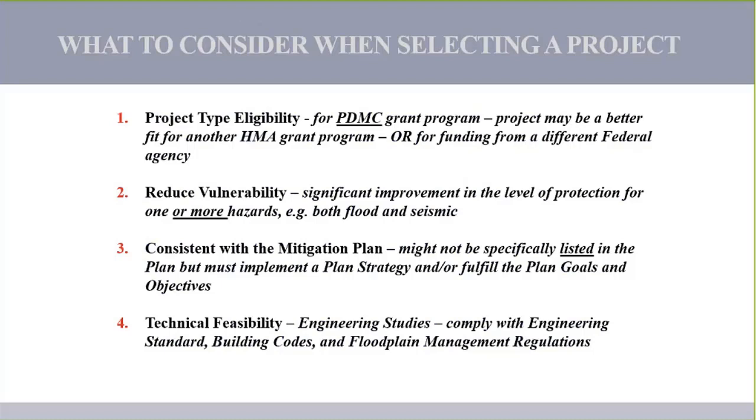Reduce vulnerability would be your second point here. Make sure that your level of protection for whatever your hazard is an improvement. Are you putting a culvert in that's, let's say, a 20-inch culvert and replacing it with a 20-inch culvert? That's just a replacement. That's not an improvement. How are you improving the level of protection and reducing your vulnerability by doing that?